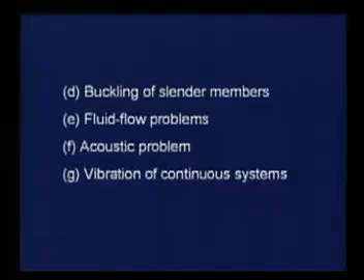In many problems, especially with respect to thin or slender members, there is an issue of failure which has to be analyzed along with the typical material failure, which is buckling. So buckling of slender members is of great engineering importance from the point of view of designing members. Buckling can be studied quite easily using the finite element method.